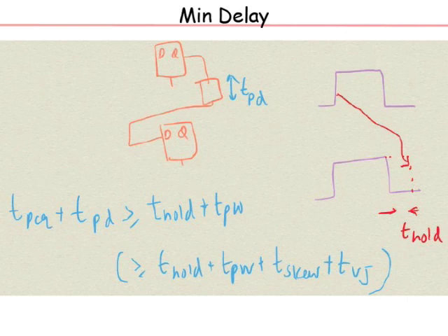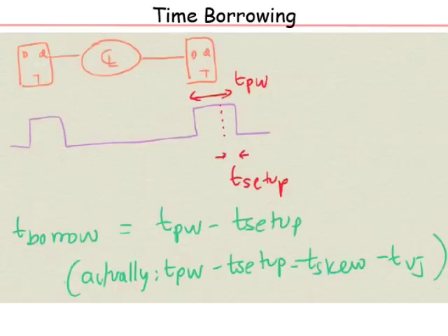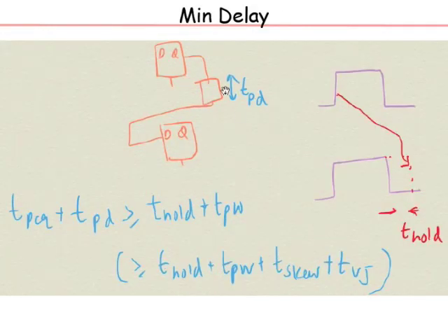The whole time is basically from the clock edge which is capturing. In the latch, it is with respect to the falling edge, because the falling edge is the one which is causing the latch to go from transparent to opaque. So, the whole time, the latch should be transparent. So this is what we are seeing.